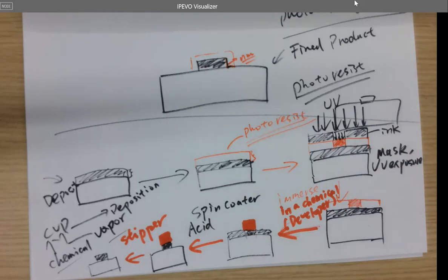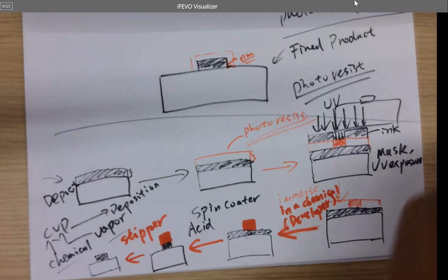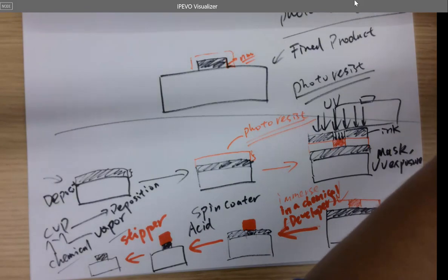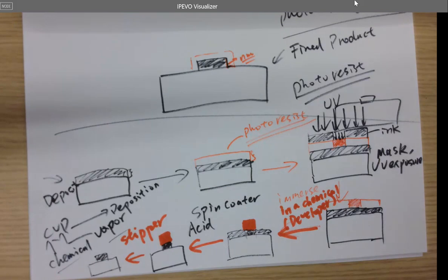So in my senior seminar, when I was an undergraduate, what I did was I bought the double layer metal plate, which is the PCB board originally. It doesn't have any circuits on it. It's just the copper plates on the bottom and top. Okay, and then I designed the circuit, just drew it with any of the paint tools on the computer, and printed it out using a plastic film, I think. It's glossy plastic film. So the ink is not absorbed by the paper. The plastic film will keep the ink outside of it, right?